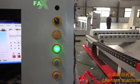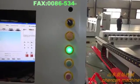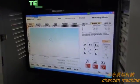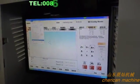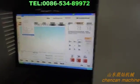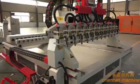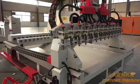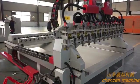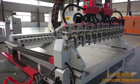So now we first send it back to home. Usually we use here, back to reference point. You can watch the machine moving. First it moves the Z back home, and then the X, and also the Y and the A, the rotary.